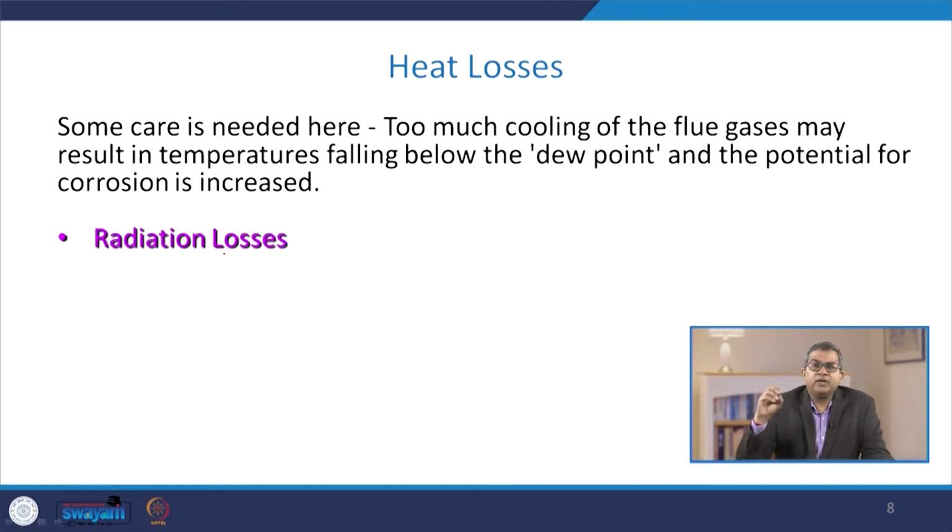Again, some care is needed. Too much cooling of the flue gas may result in the temperature falling below the dew point. We have already gone through this dew point concept, and the potential for corrosion is also increased. So, it is the responsibility of the engineers to maintain the flue gas temperature at an appropriate level, so that either corrosion or excessive heat loss can be avoided. Apart from this, since we are maintaining a very high temperature in the boiler, there may be significant chances of radiation heat losses, and it is very rare to avoid these losses.